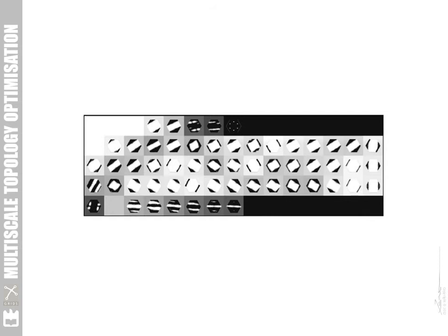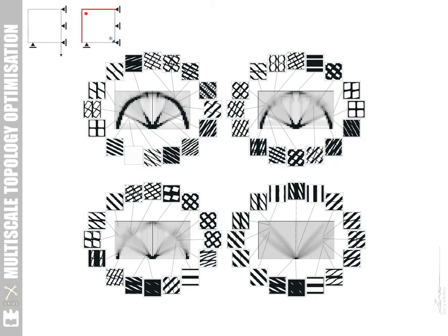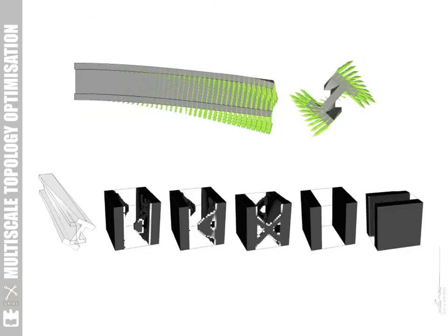There are hexagons, which is different. And here another example, where we take the purely mechanical problem with some examples of optimal microscales. And we do basically a multi-objective optimization, where we gradually impose more and more of the thermal problem. Here we have a 3D case, just as an example. In this case, what we have is one microscale for the whole case, and we oscillate between each one of the macro scale problems that you see, both in terms of isolated solutions and in terms of multi-load solutions.